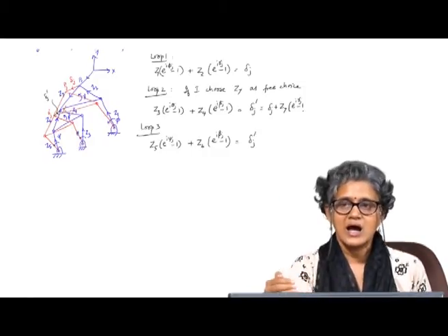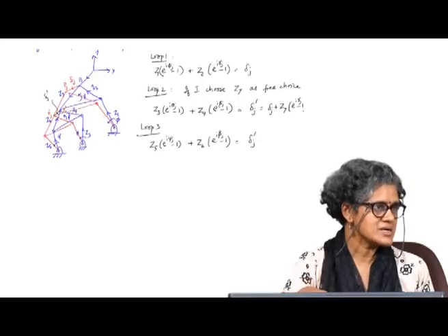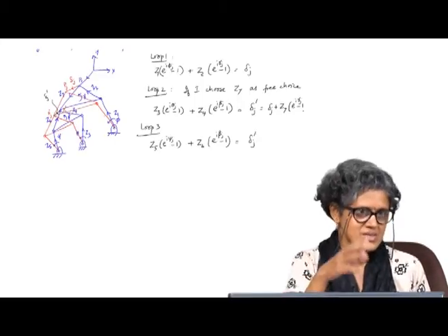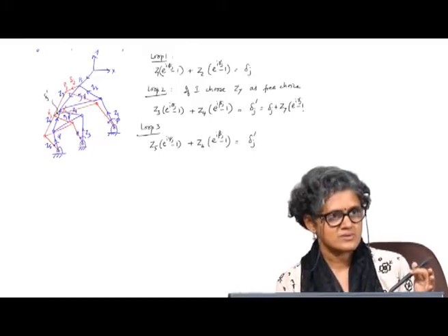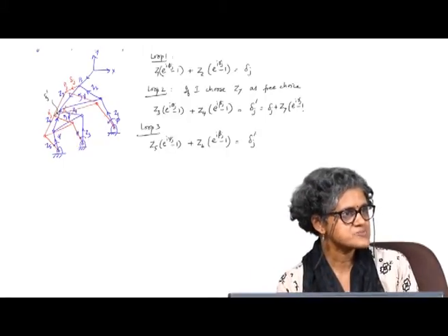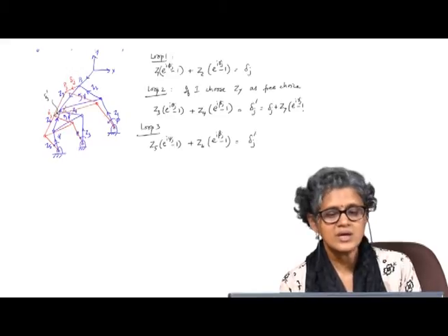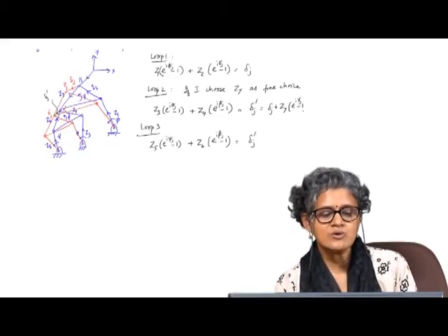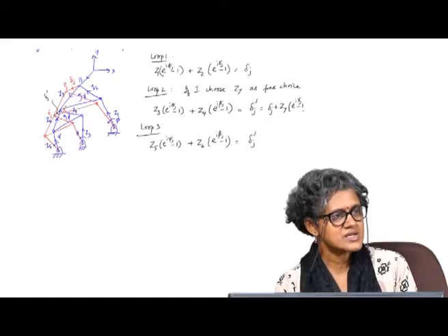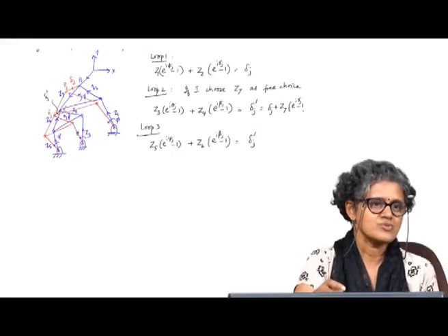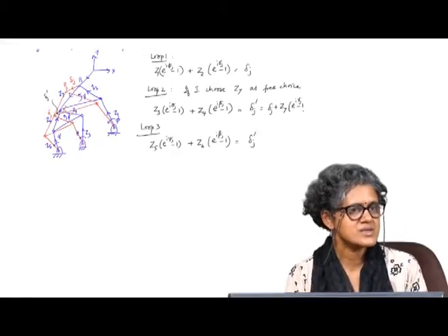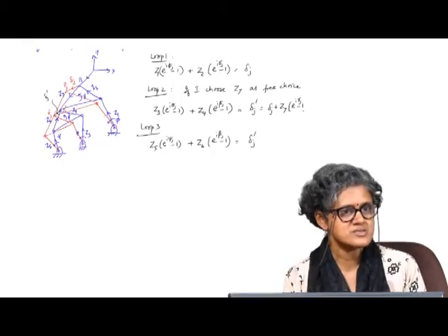Choosing z7 gives me lots of options now. After I choose z7, I get these three dyad equations, and then I have free choices in them depending on the number of positions. So, you can see that my number of infinities of solutions starts expanding. The other advantage is I can now synthesize simultaneously for function generation and motion generation. So, I can do this dyad for motion generation and also link theta j and psi j for instance. So, I get more options.